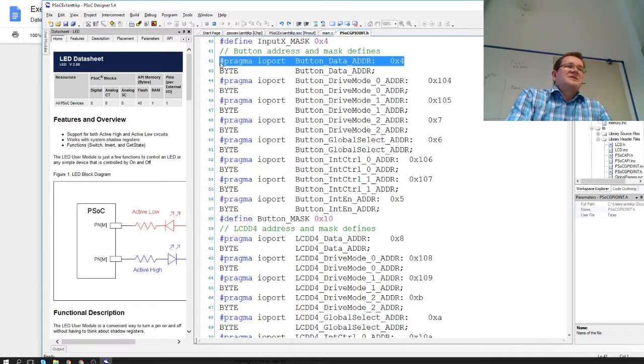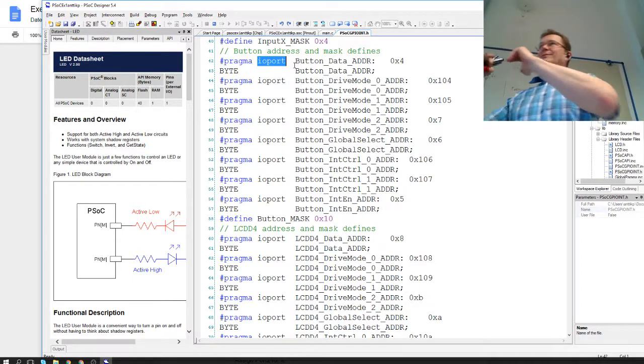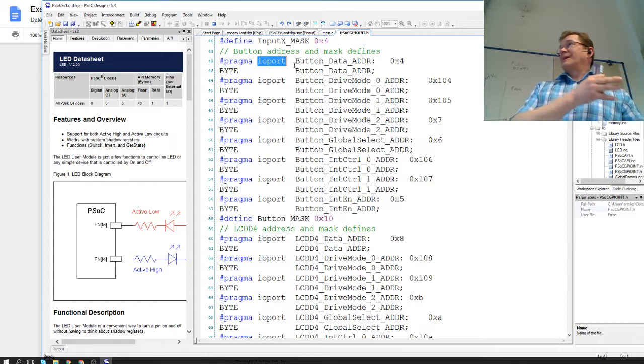This here is a pragma statement. Are you familiar with the pragma statements? That's just a compiler directive saying that this is not a standard C kind of thing, but something else. In this environment, it means that we can have, for example, I/O port definitions, since those are on a different address space than the normal RAM addresses or ROM addresses.